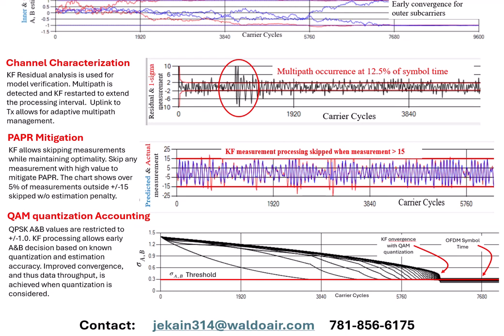What's next for our development direction? We are working towards a hardware demo of the new approach and will emphasize channel characterization. We are also working on a high-Q digital bandpass filter that will be integrated with the demodulation filter. This will both reject neighbor communication channels and will allow data population of edge subcarriers, also making use of subsampling.